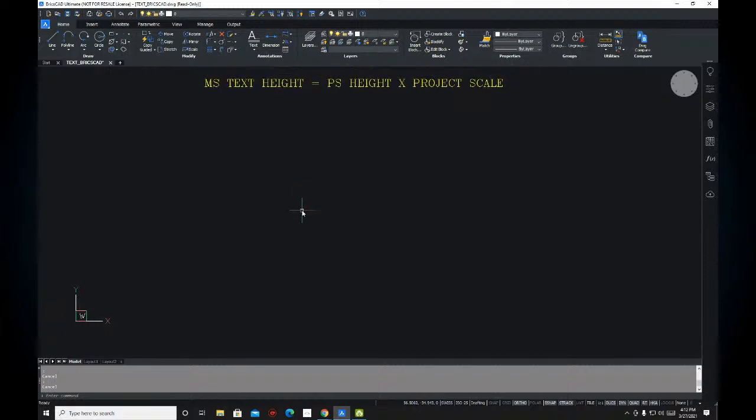Our alias for dynamic text is DT. So that is the text I will accept. Then we have here settings right below. So we have use defined, align, fit between 2 points, and so on. Currently, we don't see the other justifications here.